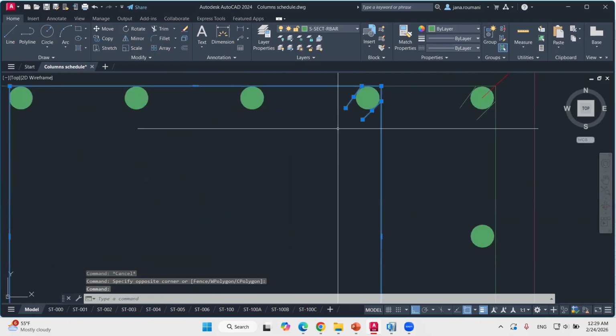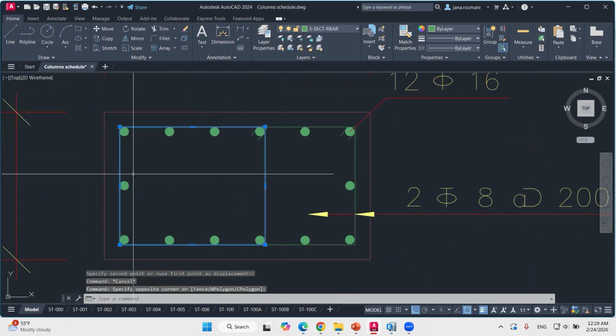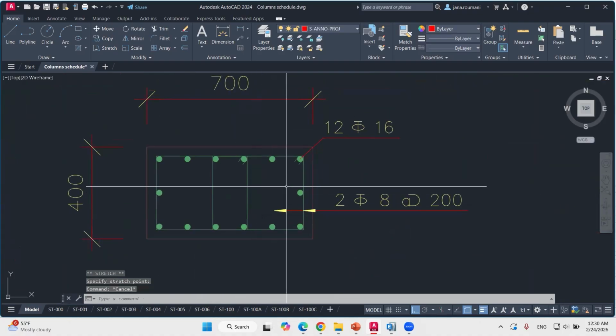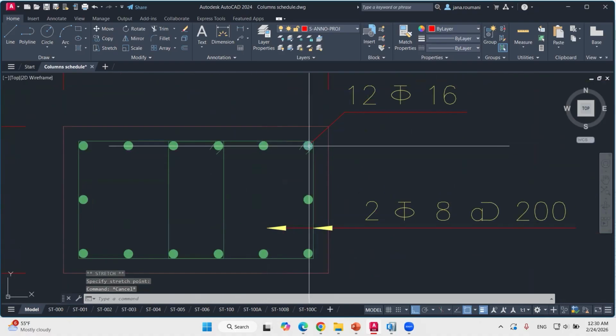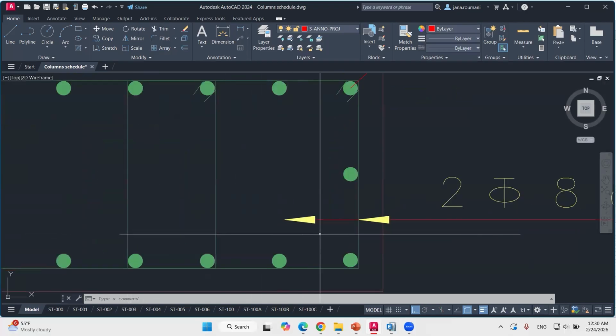So the better thing to do is to keep the symmetry. We can do this stirrup. Okay, so here we have tied, not tied, tied, tied, not tied. Okay, so we don't have more than one row of stirrups untied.